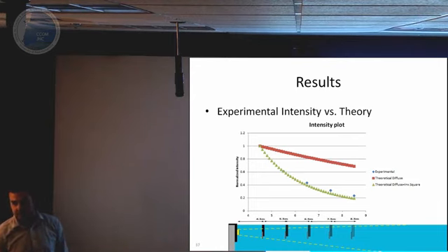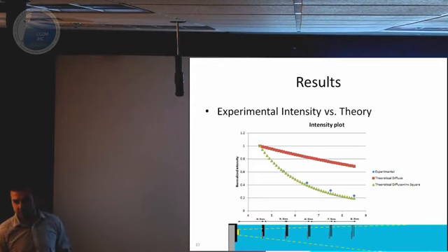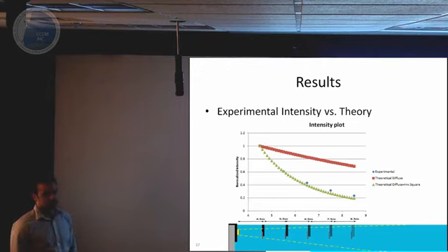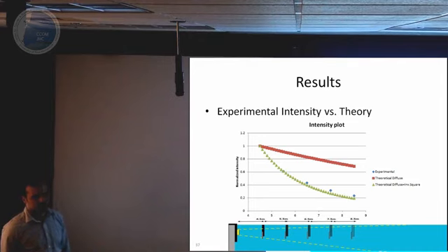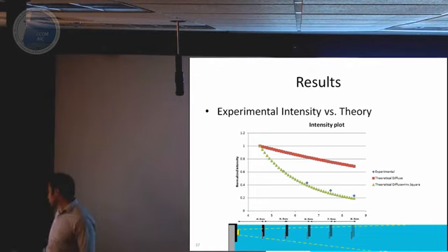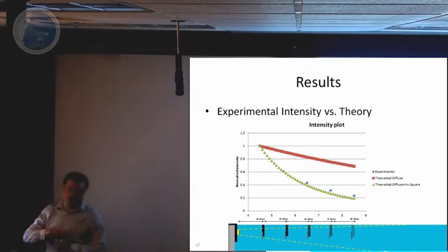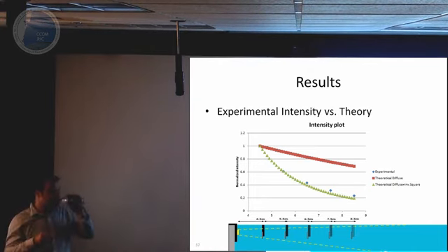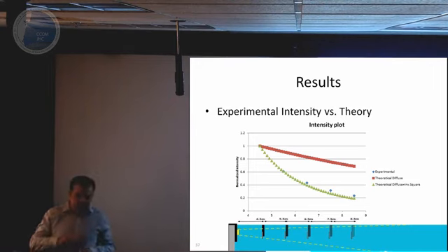Right, and you can change that deployment during the task. You can program the vehicle to change it over time. And if I may add to that, a lot of times people don't realize that even if you're manually controlling an ROV, that itself involves feedback control, because what you want it to do and what it actually does is totally different. So it takes into account the difference between the leader and the follower, so it's actively trying to follow it regardless of the situation.